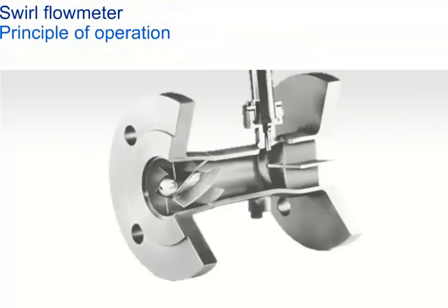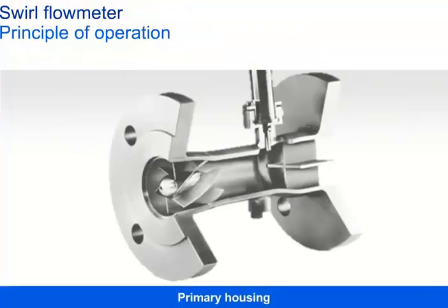Principle of operation. The swirler is solid welded and has no moving parts. The same sensor and the same electronics are used as for the Vortex Master flowmeter. The D-swirler is located near the device. It forces the medium back to a well-developed flow profile in order to avoid further pressure drops behind the flow meter. Swirl flow meters also cause oscillation of the medium to determine the flow velocity.